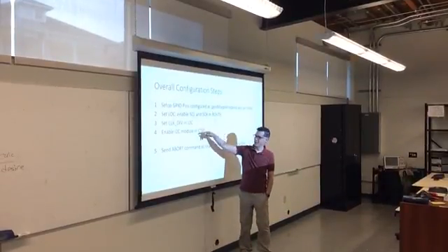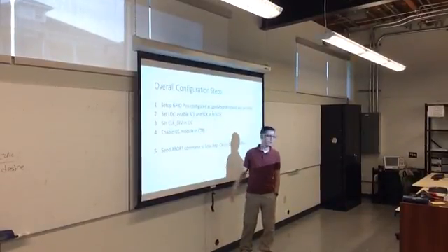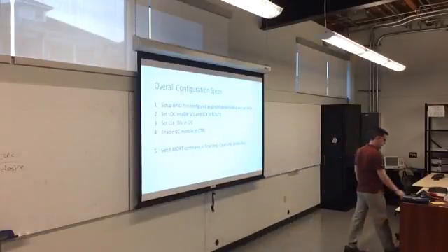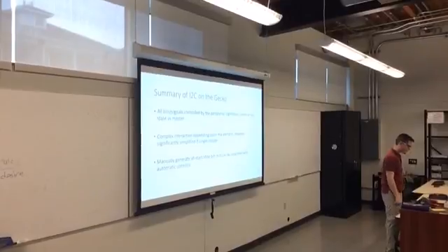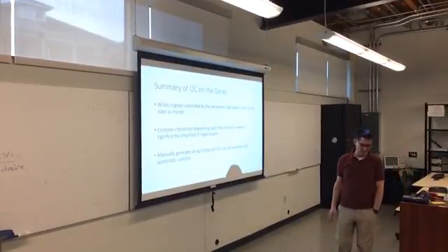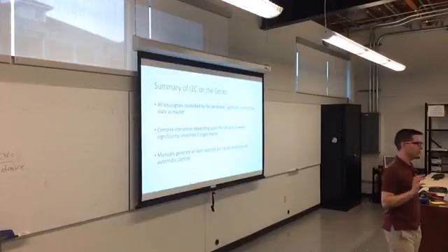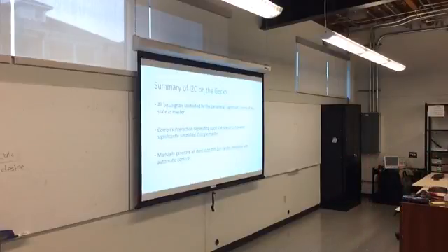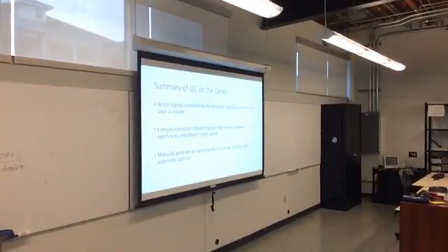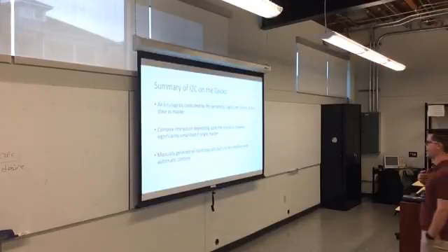All right, overall, I2C from the get-go has a lot of configuration that you have to do. You've got to send your own start, stop, ACK, NAC, and data bits. You've got to send them all, but there are a lot of registers that tell you the current state and status of the bus. You can simplify things with automatic controls, but we're not going to use them. You're going to do these manually. It's not as complicated as it looks because you're going to be the only master.